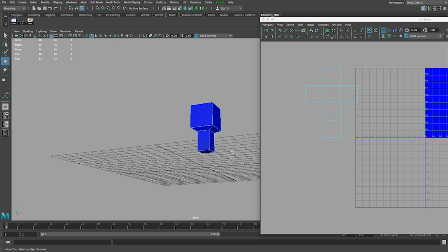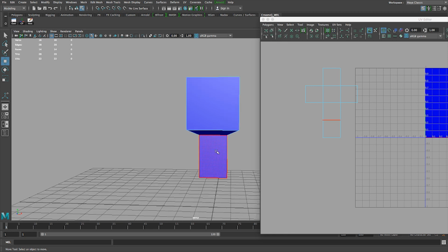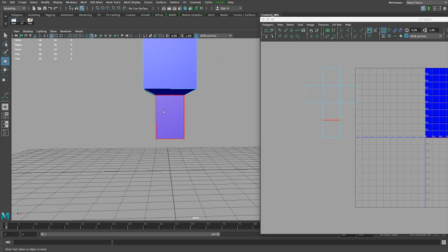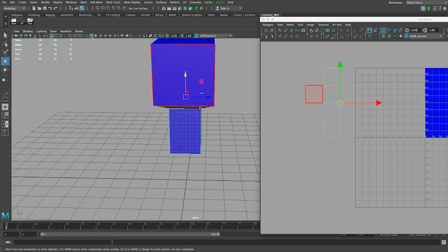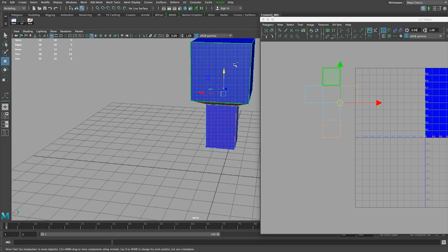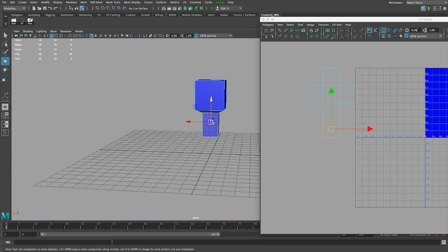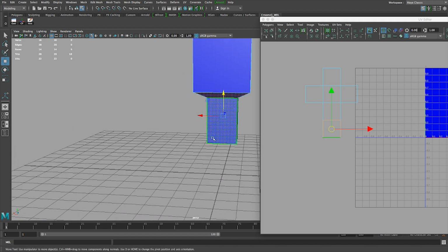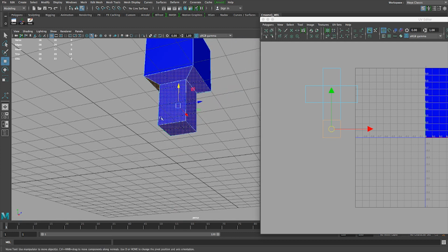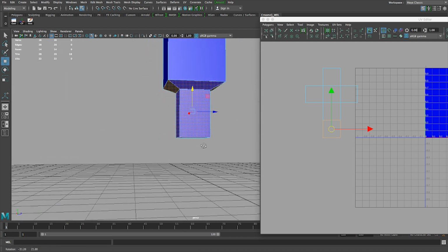I can also just go here and that will work just fine. If I do these selections, usually you should do it in orthographic. But I can also just marquee select the bottom. I got the same result pretty much. But you see here by mistake I selected this and also this. So the only thing we need now is to select all these other new faces that we created with the extrude, right?